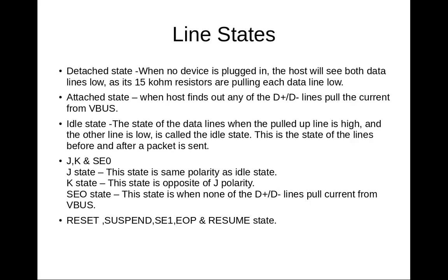In this suspend mode, you use single-ended zero for about 10 milliseconds. The device, after 5 microseconds, will know it has gone to the suspend state. Now if the device goes to suspend state, it should have some protocol that sends a resume signal, saying I'm ready, I have something to send.